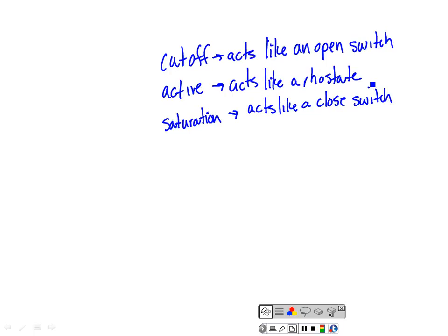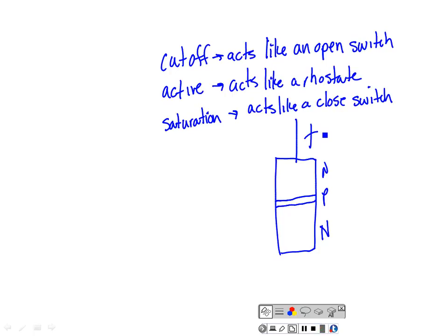Now, when we forward bias this thing, and we'll look at the NPN, I need to put a big positive up here, and then a little positive right there, and then if this right here is positive, it's got to be even littler positive. And we're going to do that before long. As soon as we forward bias it, we have current flow: a little bit of current flow that way, and a heck of a lot of current flow this way.